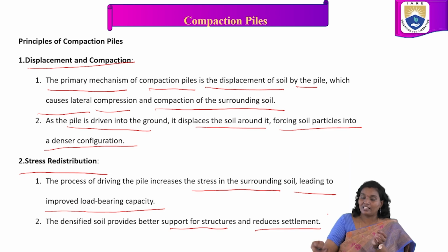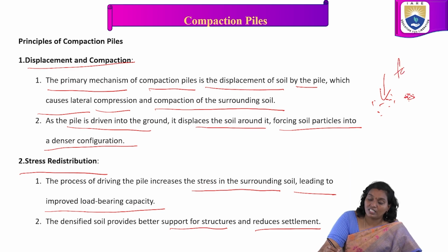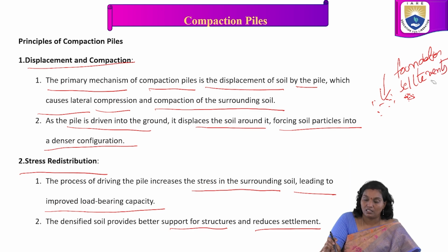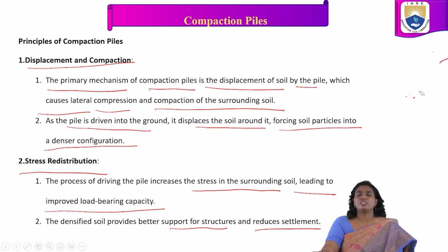Once the soil is like this, the density is like this. Once the compaction pile is introduced, the particles are maybe like this. It means it reduces the foundation settlement. So stress redistribution, displacement and compaction are the principles behind these compaction piles.